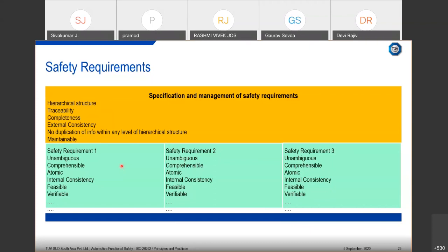And then coming to the requirement management aspect, the ISO also brings the importance of having various attributes for each and every requirement. That is also one of the very critical and important aspects, I can say. So basically, for each requirement you will have the ASIL level of that, and the status of the requirement, whether it is already approved or reviewed, or whether it is a draft, or whether it is a TSR level requirement, or maybe software level, hardware level, and then how this particular requirement can be tested, at what level it can be tested.